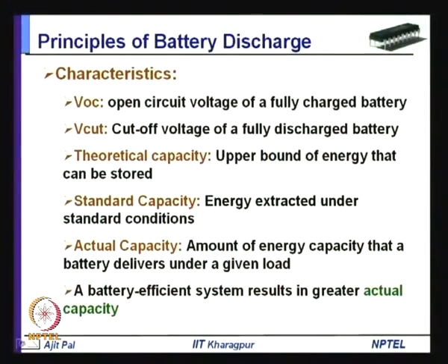Those who use cars know that in most situations the car battery fails in winter. The reason is that the temperature is low at that time, and as a consequence the battery is not capable of giving high current.